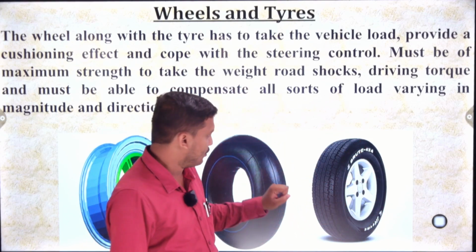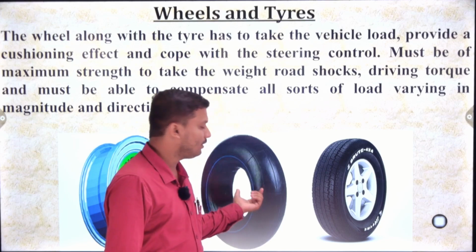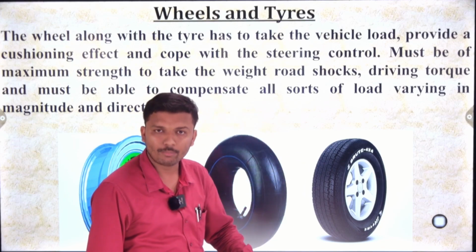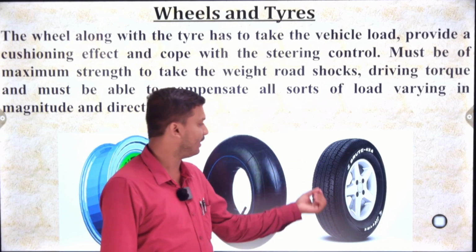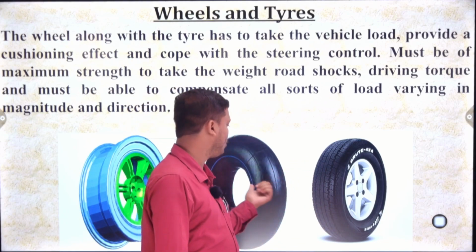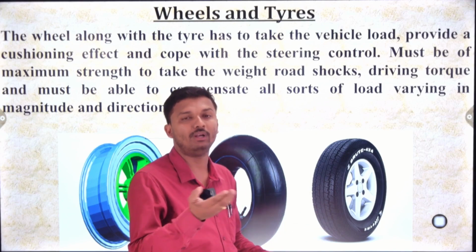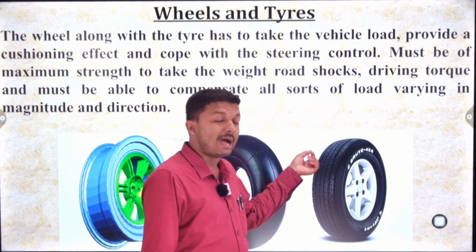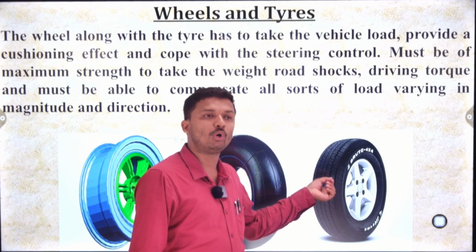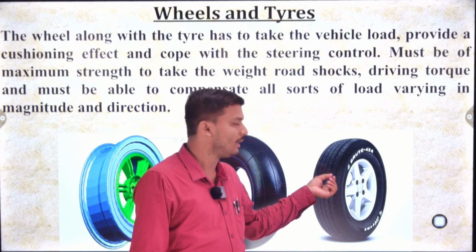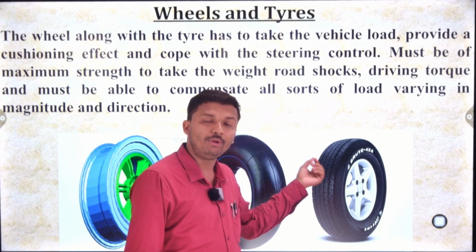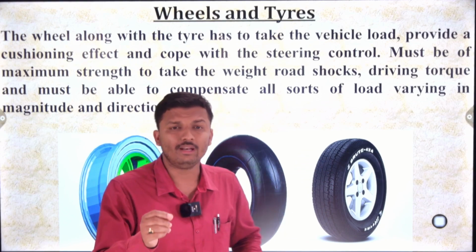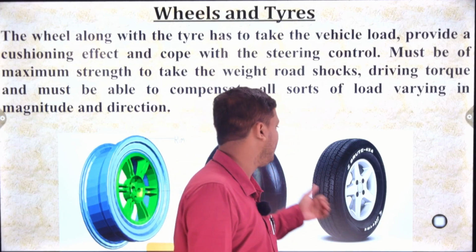Similarly, in this tire, what happened? The air goes out completely and very abruptly. The puncture takes place at an instant of time. You cannot move forward. But in the tubeless tire, what happened? There is no tube, and the tire contains a number of small layers inside it. After the puncture, you can move forward a lot of kilometers, because the amount of air flowing out of the tire is very small in comparison with this.